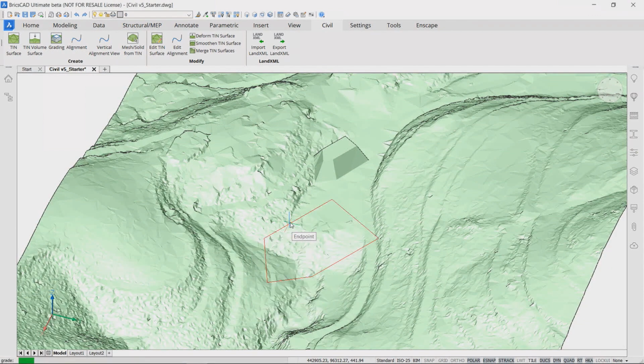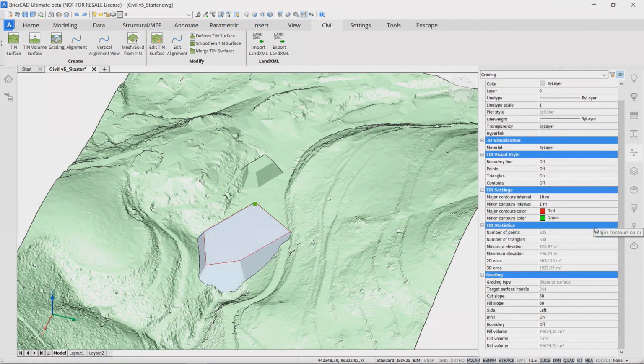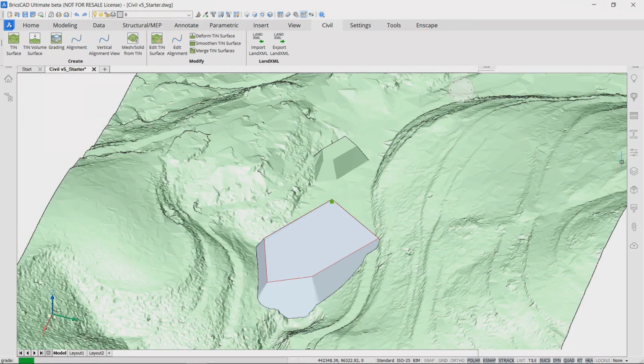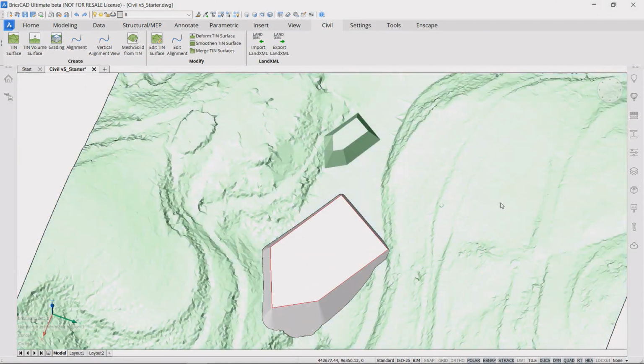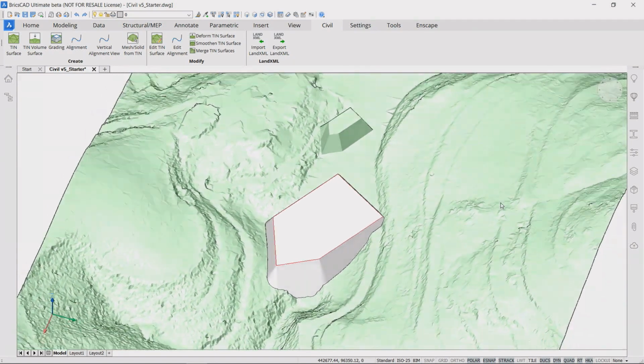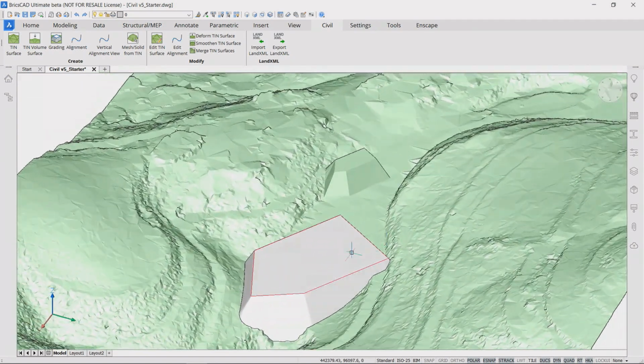But when we know the footprint, and we know the slope, then we can use the grading technology. The grading technology helps you to create the side slopes with a certain angle to find the intersection to the existing ground, and such an irregular geometry is created.